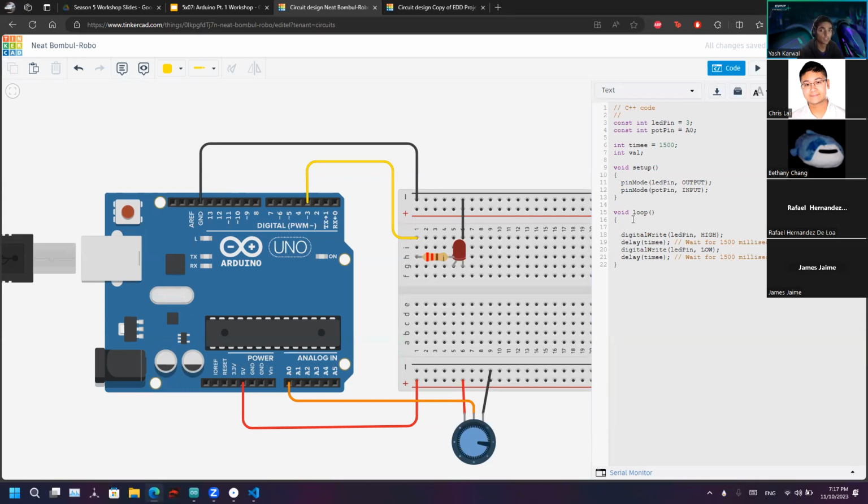Blink faster? Okay, do you want to make it blink faster, but at a constant where the time low and time high are the same? Do you want to vary both of them, so that the more you turn it, it stays on for longer, basically doing a PWM signal but with just a potentiometer? Do you want to do both? Change the brightness and the blinkiness? There are a lot more options now. Both? Okay. So let's do both.